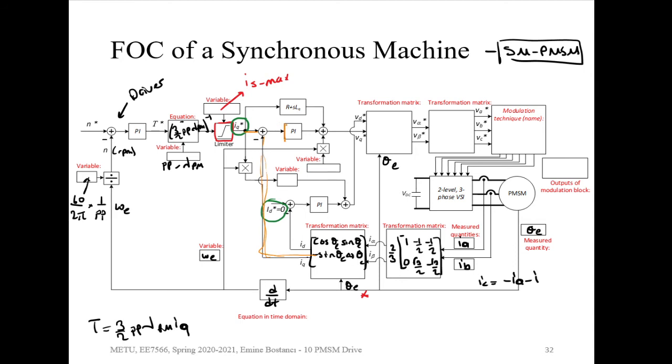I'm just going to have the PI controller to control the IQ. This is the first thing. And I will have the same thing for the ID: ID measured, with a minus sign, and there is going to be the PI control. The rest is going to help with my VD and VQ approximation, the VD and VQ calculation.